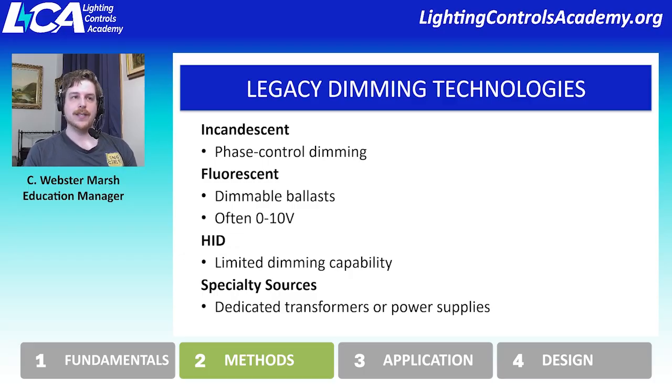In comparison to at least HID and fluorescent, we've seen a lot of benefits in ease of use. Incandescent, it's debatable. A lot of people say incandescent dimming is so much better than LED for a number of reasons, but we've actually seen the innovation of LEDs with quality dimming and the correct communication protocols in place that we have actually high quality dimming that is competitive with incandescent dimming.